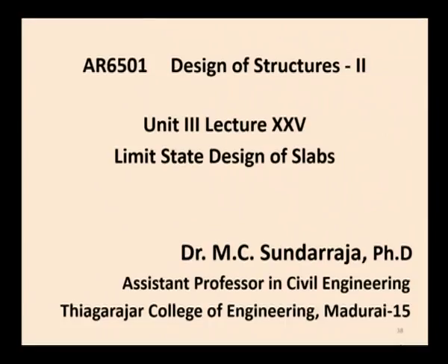And also we saw in detail the design guideline requirements for the design of slab as per IS 456-2000, starting from the effective span of the slab, the total load acting on the slab and the moment, then the arrangement of reinforcement, that is, what is the maximum spacing of reinforcement and what is the maximum diameter of the bar. We saw that in detail in the previous lecture.